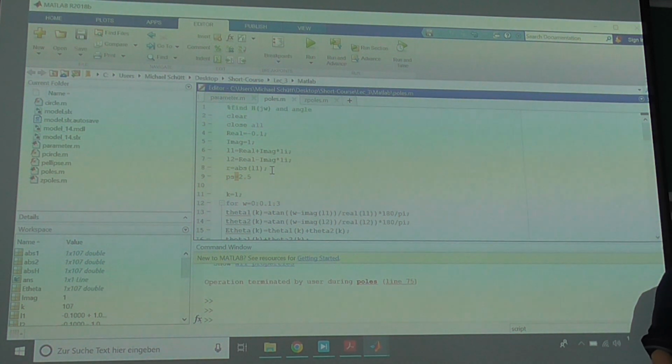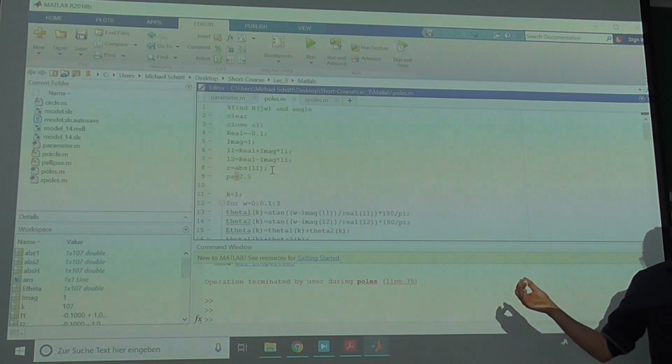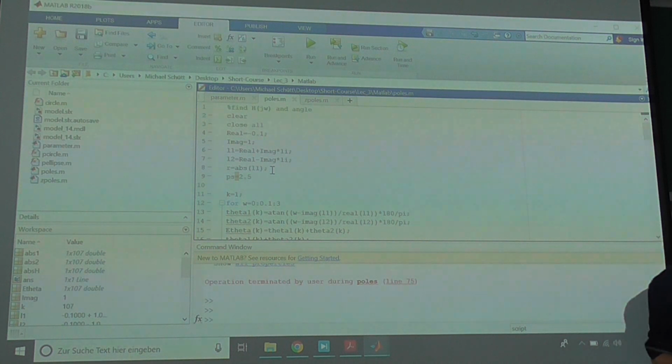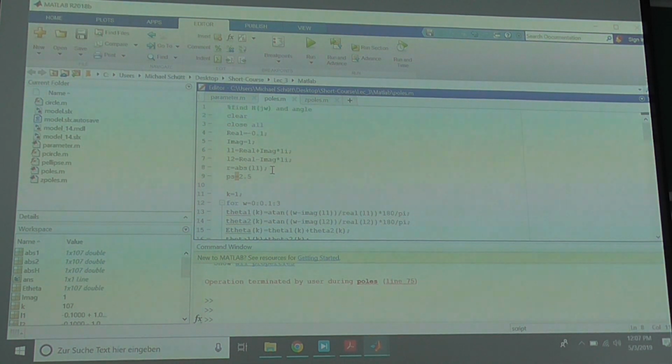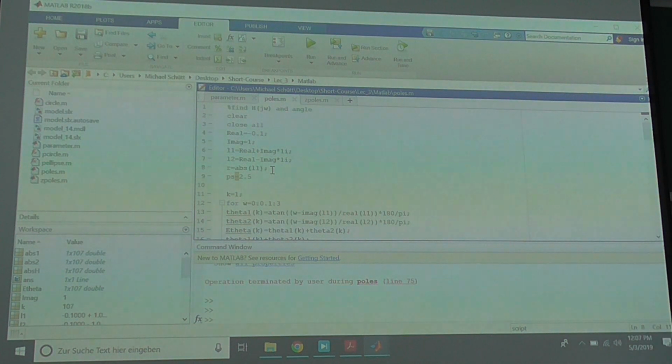Because this is all math. We don't run into voltage issues, right? That's math, there's some energy involved. So we can choose any bandwidth we want. But why don't we do it? If the bandwidth is really high, how good is the filtering? There's almost no filtering if you have a lot of bandwidth, right? Yeah. So increasing the bandwidth makes our filter worse.